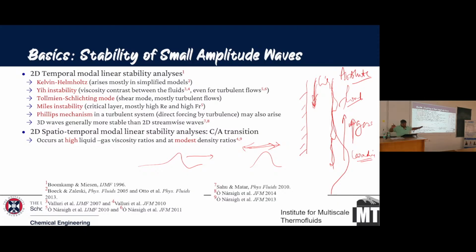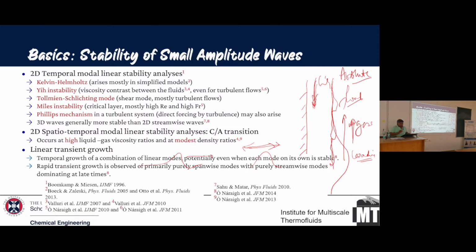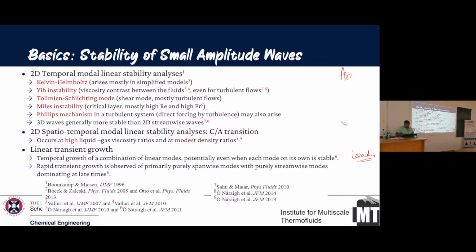So you can imagine when your column is flooded, the whole column is completely flooded with liquid, and it becomes inoperational. This is the character of the instability. Whether your system is convective or absolute is an important thing which people look at, especially when designing these systems.